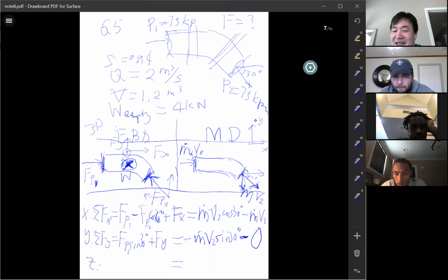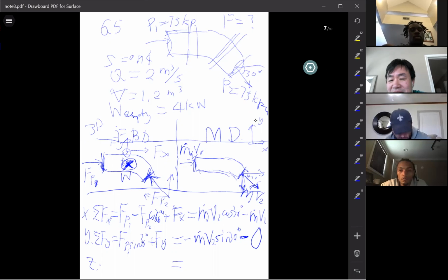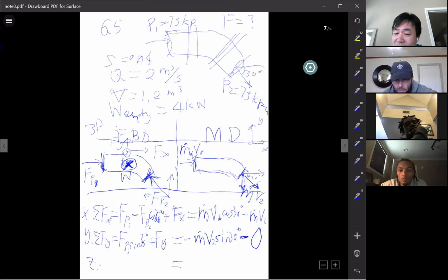Although it's not the energy equation, you can still think like this. You have momentum coming into the system, but because of the bend, some leaves in the x direction, and some is directed into the y direction. But for solving problems, you don't need to worry about this. You just separate the equation in the y direction and the x direction, and look at the momentum separately. Yeah, Dylan, you have a question?